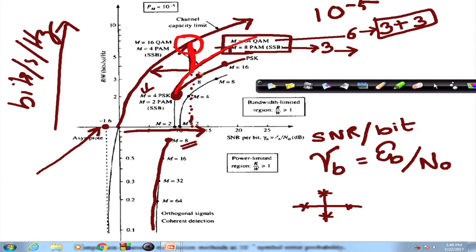If we want to see the capacity gap with PSK, we have to refer to this particular curve, and we have to refer to that for M-ary orthogonal signals, of course, how this curve extends there is what we have to see. The other way of viewing this curve would be that given a particular spectral efficiency, what is the excess amount of Eb/N0 required to achieve that.